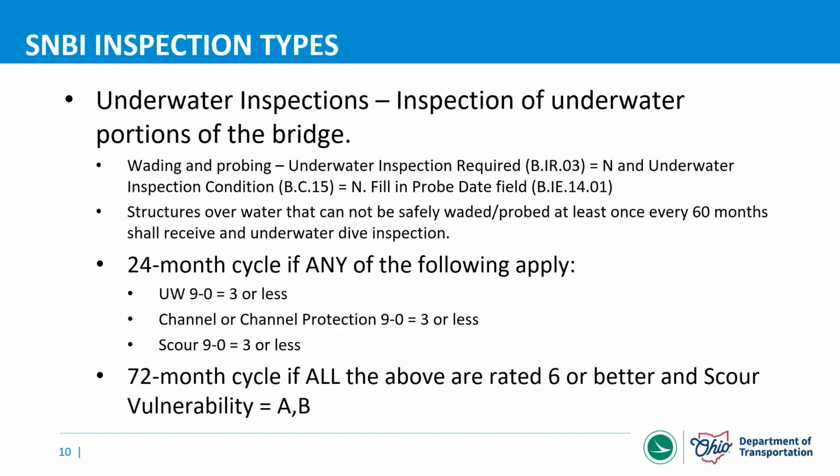So remember that wading and probing is considered by Federal Highway, or by the definition in the BIRM, as an underwater inspection, but you do not need to fill out underwater inspection required. That is specifically for underwater dive inspection. So I understand that that's not the clearest, right?